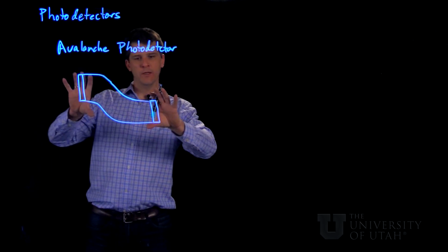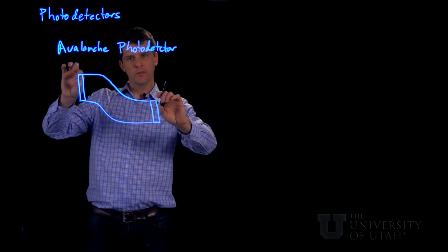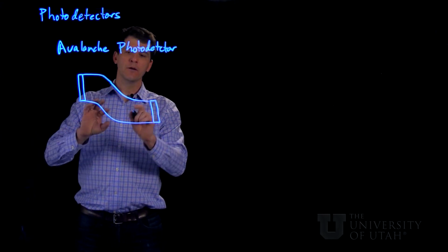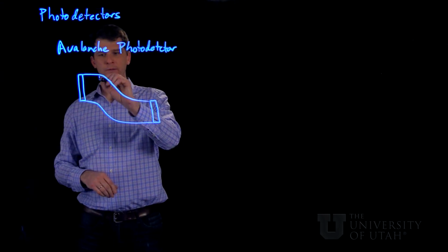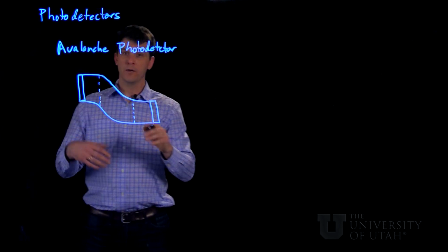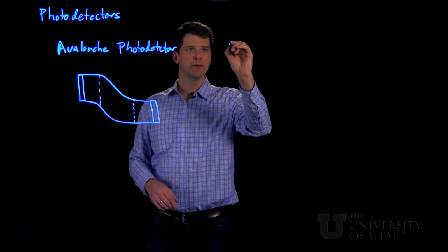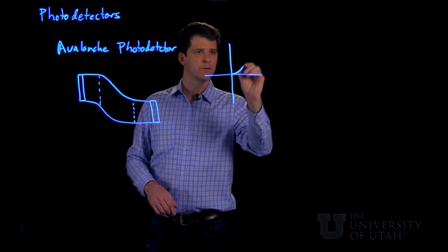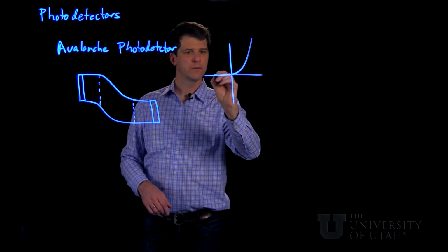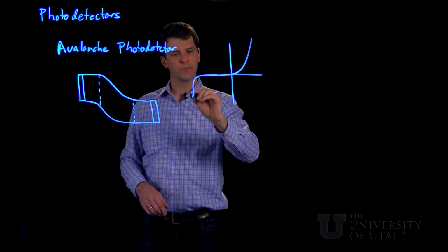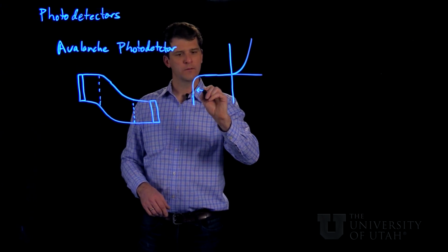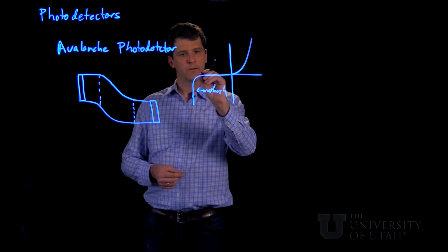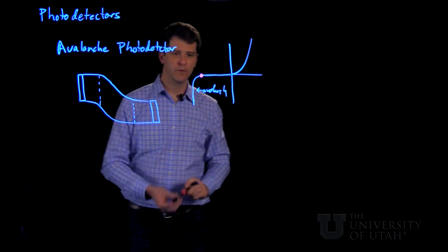Let's just assume then that you have the bias condition such that neither electrons nor holes that are thermally generated inside the depletion width will cause reverse bias breakdown. So here we're talking about in the dark, the part of the avalanche breakdown here. So our operating point is set here before this happens.